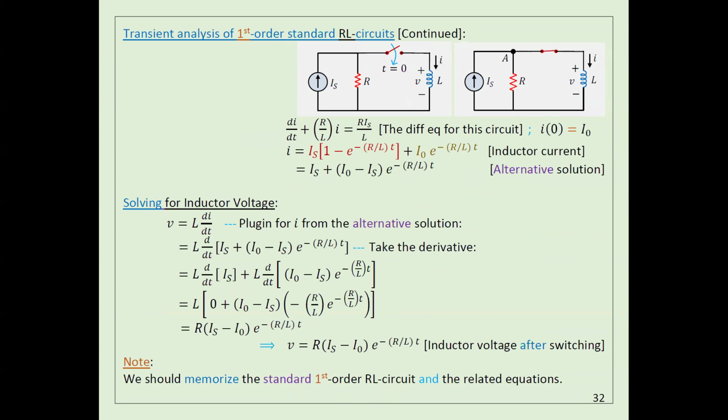So to calculate V, I need R Norton, I need IS, which is I Norton, I need I naught, the initial current, and I need tau here, T divided by tau, or R divided by L T, whatever it is. So R Norton times L. So you have one or two solutions. If you have this equation, you can differentiate it to get this one here, or you can just use this formula. I prefer to just use this formula to get the voltage at both sides.